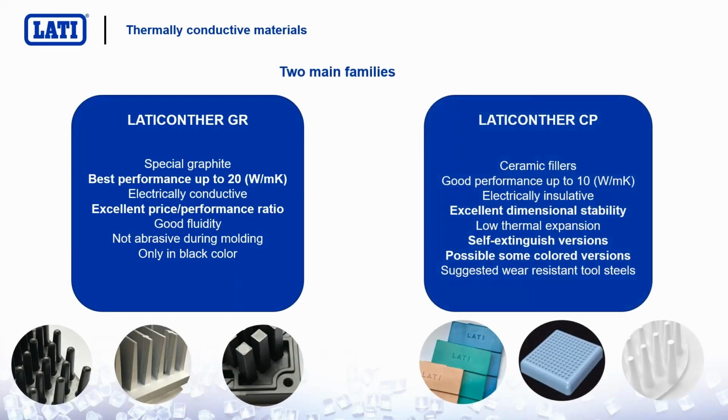Here at LATI, the thermoconductive materials are identified by the family called LATI Condor. We have two main subfamilies: LATI Condor GR, which features graphites, and LATI Condor CP, which features ceramic fillers. The LATI Condor featuring graphite have the best performance in terms of thermal conductivity, and they are electrically conductive also.